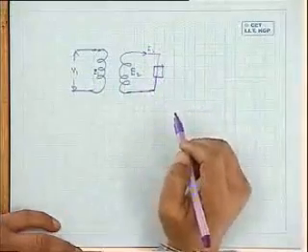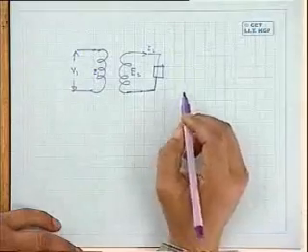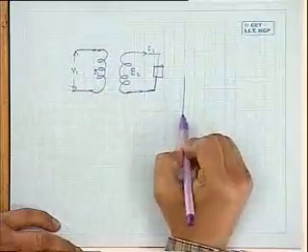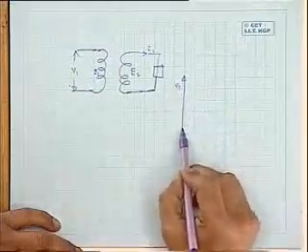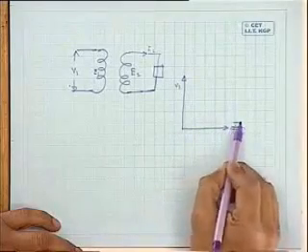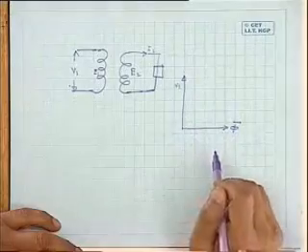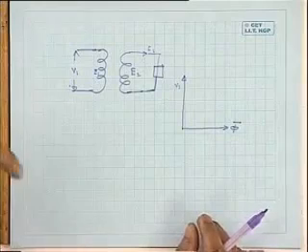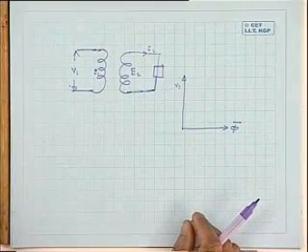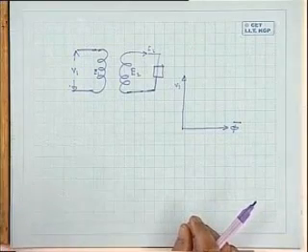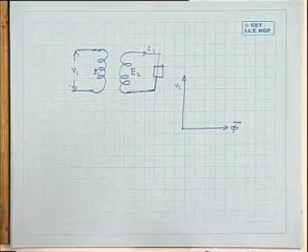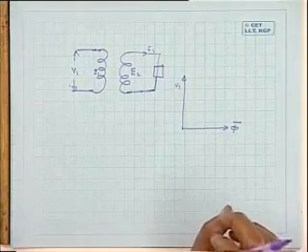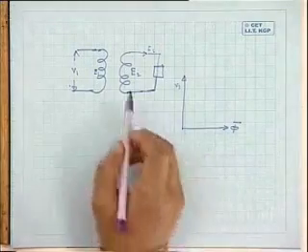Now, some authors draw the phasor diagram in this fashion, and they are also quite right. They say like this: you have applied a voltage here, V1. This is the flux developed in the core of the transformer, 90 degree lagging. Now, this induced voltage, what will be its time relationship with V1? Suppose you see in an oscilloscope, they will vary together. V1, E1, so far as time is concerned, if you look at those waveforms, they will be in time phase.